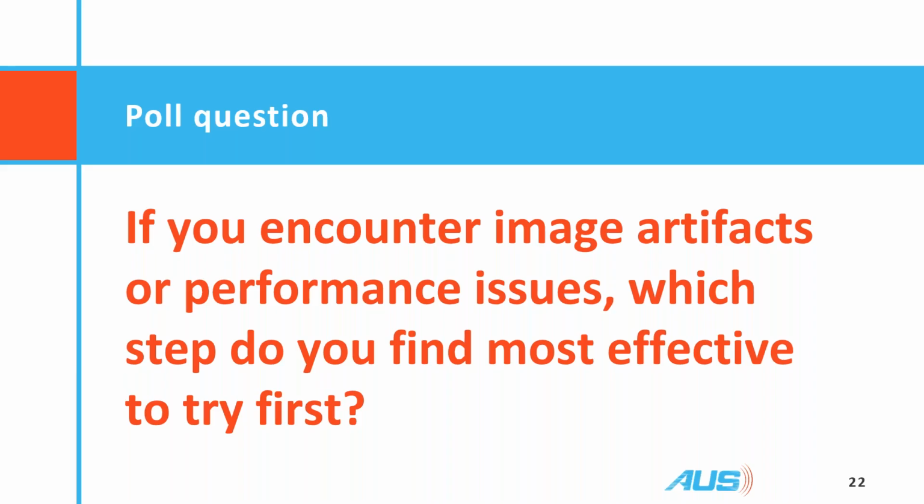If I can't, which is not uncommon, then moving it to a different system is an excellent way of confirming one way or the other. You can confirm that it is the probe, or that it's not and the system is causing the issue. So inspecting the lens and then moving it to another system is a really great troubleshooting technique.